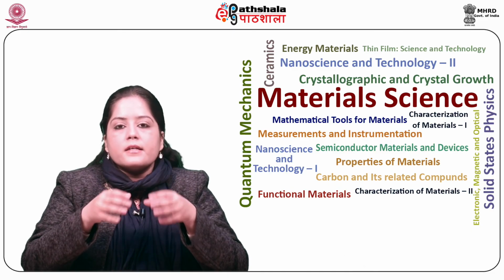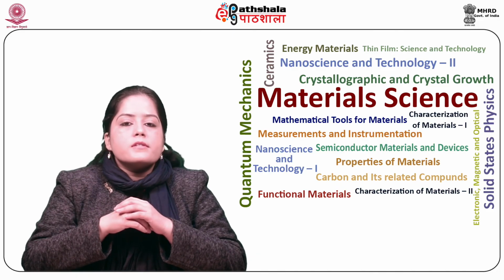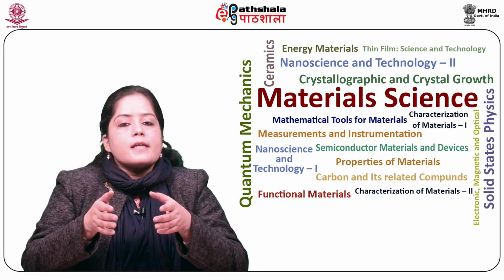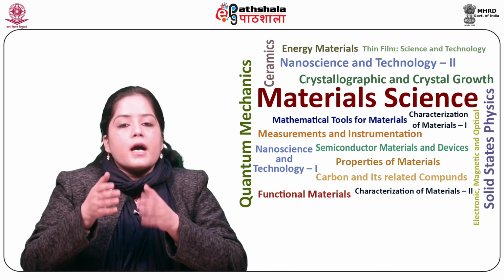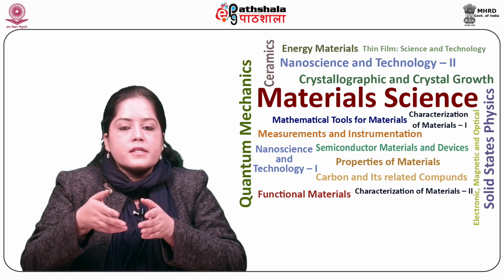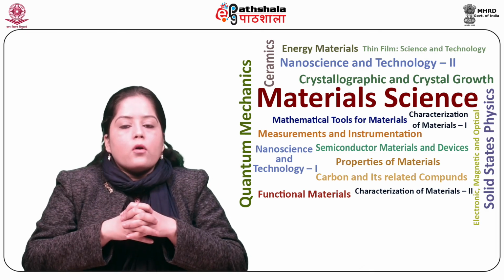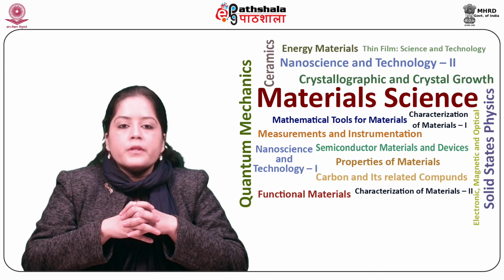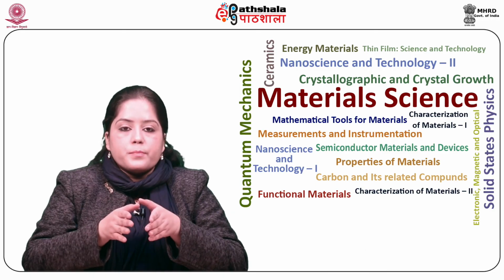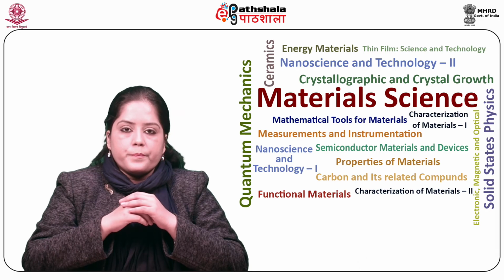Processes to fabricate nanostructured materials from atoms involve transformation processes in solutions, for example, sol-gel technique, plasma synthesis, spraying, chemical and physical vapor depositions, etc. Availability of starting materials, often termed the precursor, is a critical aspect in nanoparticle synthesis processes.